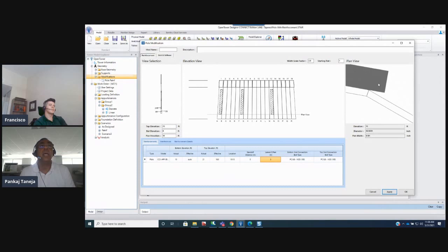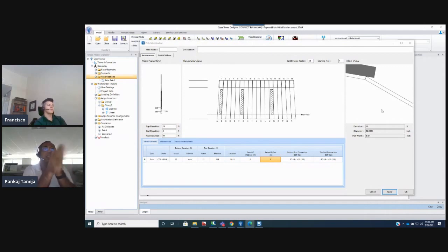So what we need to do is calculate the RW factor or RL factor, which is given in Table 2-8A in the latest addendum. All of those need to be addressed here in the wind load generation, because we're automatically taking into account the effect of the added geometry on the outside of the pole when it comes to the wind calculations, right?